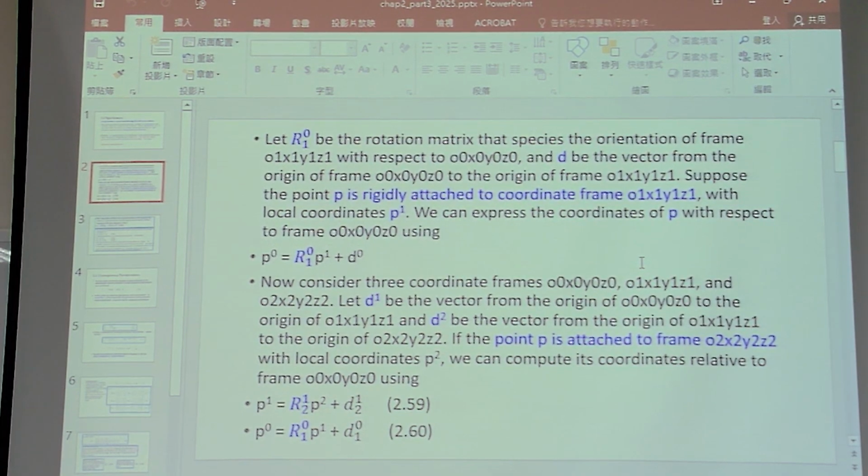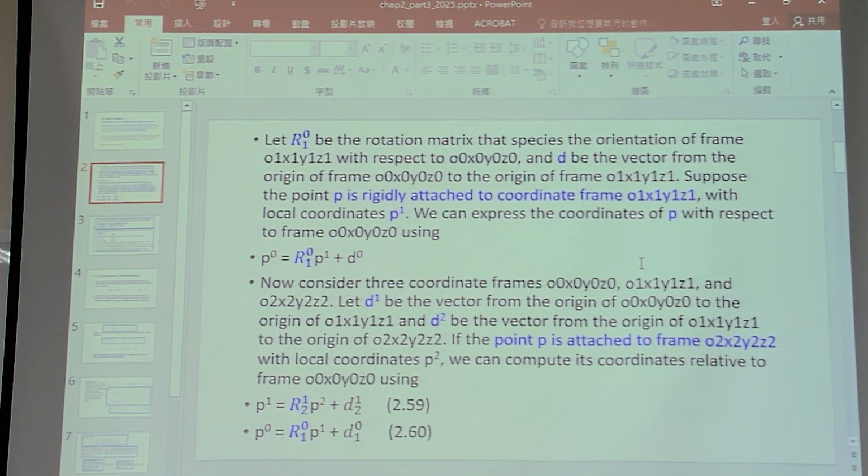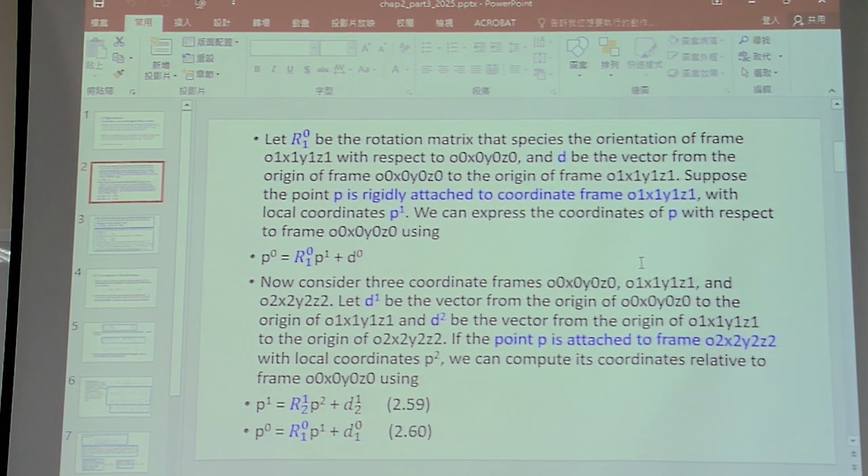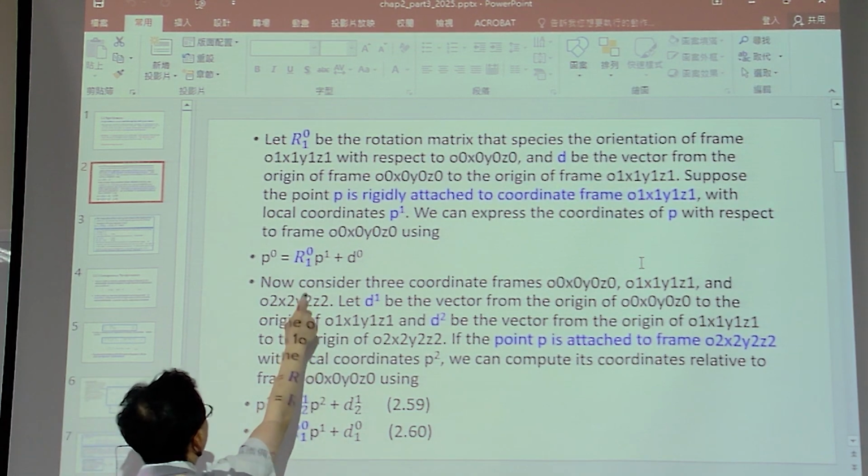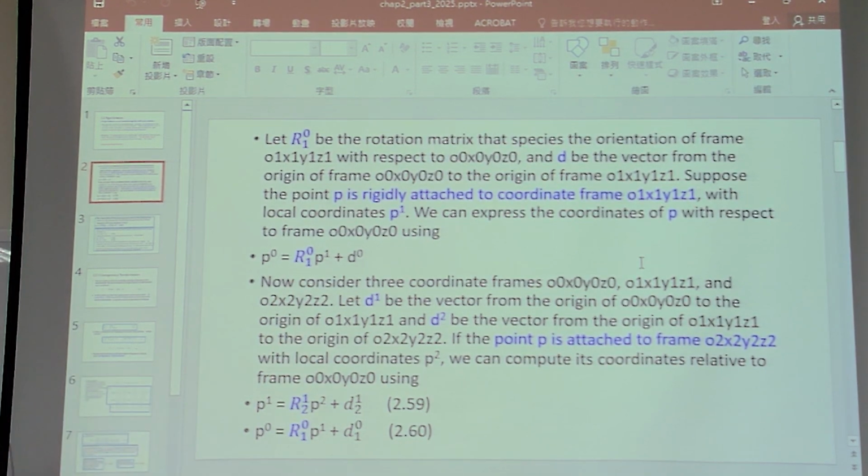The idea is we have learned everything, but we need to combine it together. We have a position, but if it is located somewhere and does not align with the other coordinate, for example, I need a z in this position but the z is in another position, then we need to rotate that z to align with my z-axis. So you need one rotation matrix for your position.